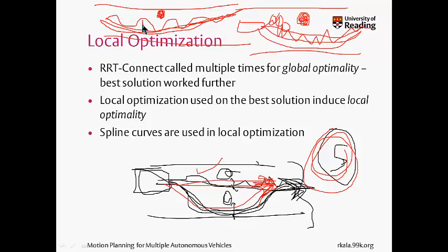If you need to transform this path into this path, you will have to do what is known as post-processing in some literature, or what's known as local optimization. This serves two purposes. Firstly, it will delete all the excess points out here. So when I delete all the excess points, I get a smooth curve where only the necessary points are there in the entire path.